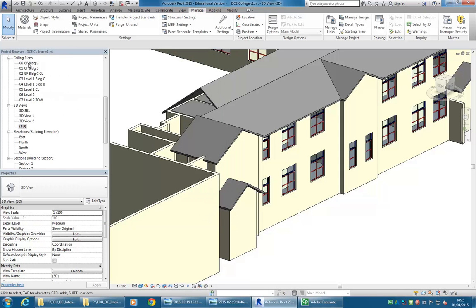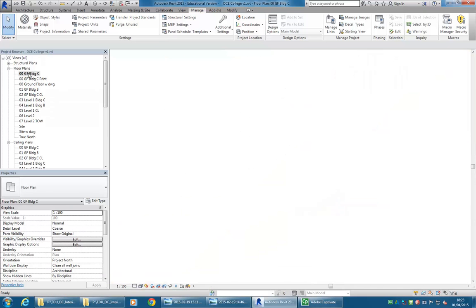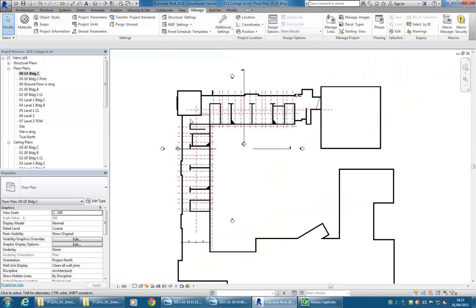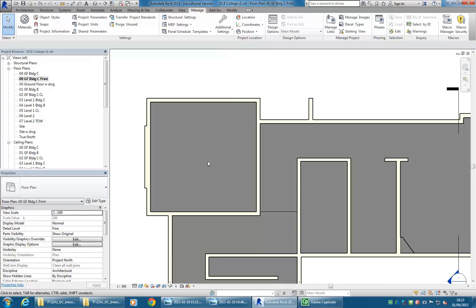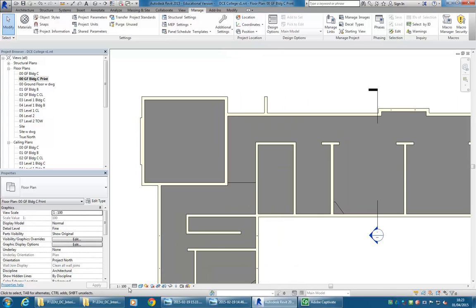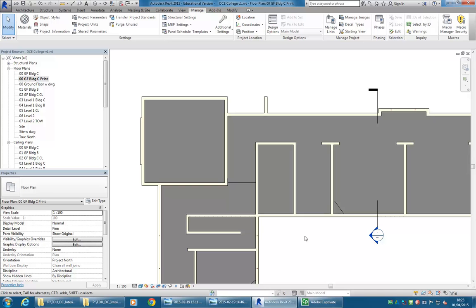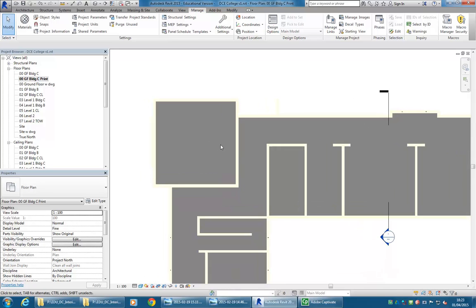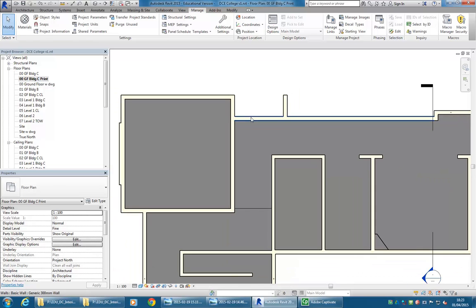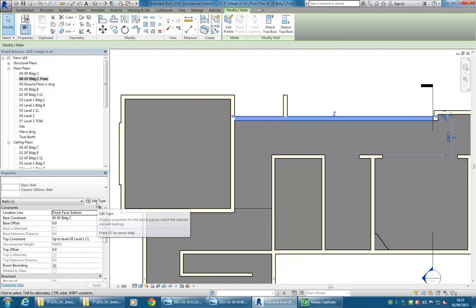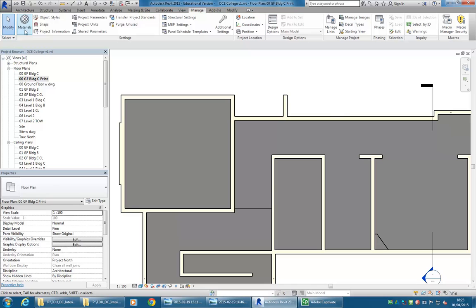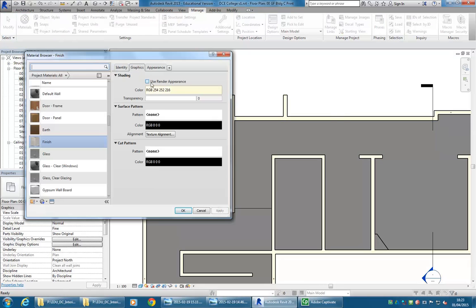So then how do you get the plan colour to show differently? So the one set for print. Okay, so it's fine if you're in coarse, you can use that coarse colour that's built into the wall. But in your fine views, which you'll need to use quite often, then you're going to get the shaded colour. But what you can do again is, sorry, just go straight to the materials. What you can do instead of changing the shading colour, you can set a cut pattern.